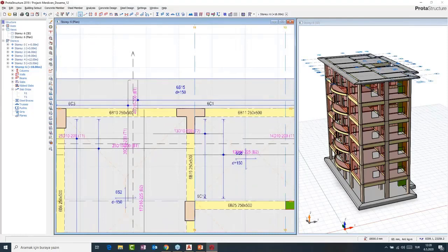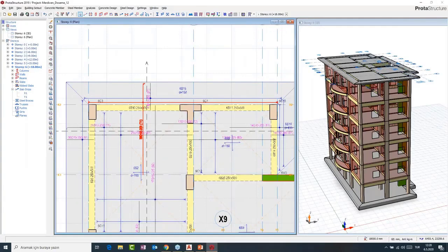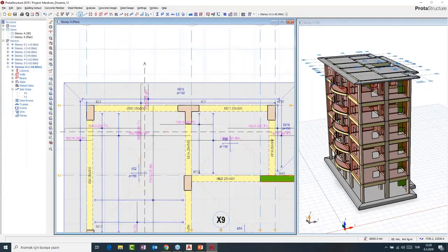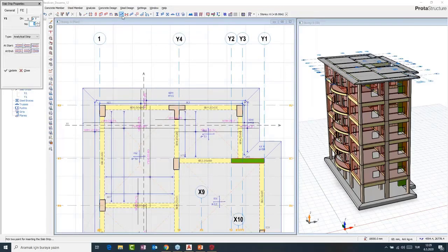You can see in here these rebars in Y direction, which I just cut the strips for, are the actual ones carrying this cantilever. Okay, so we need some rebars in X direction here that don't require any design. So that's when I use manual strips. Okay, you can come here and select what you want to use. Let's use 10 in this case.